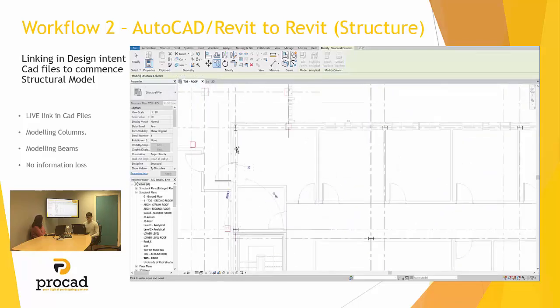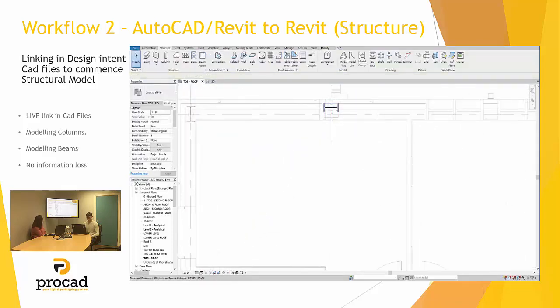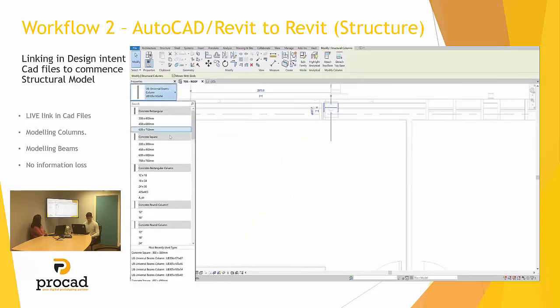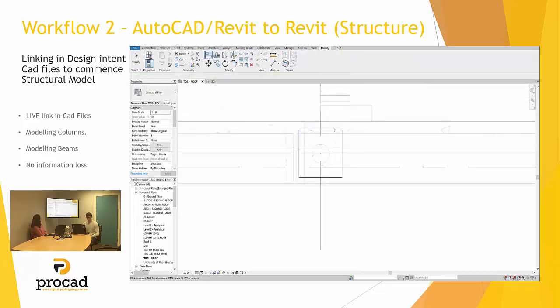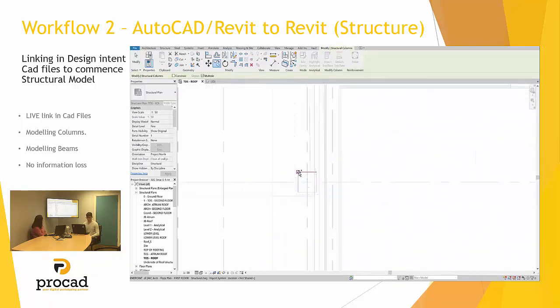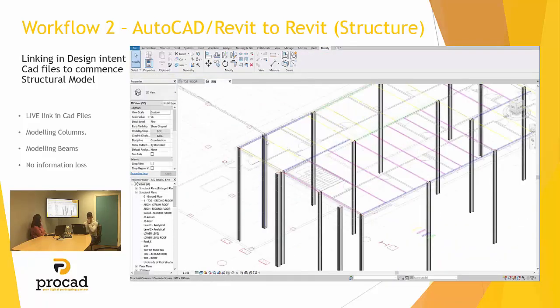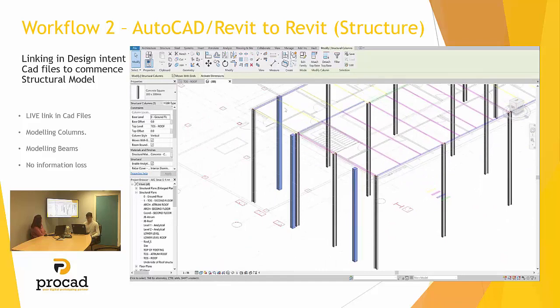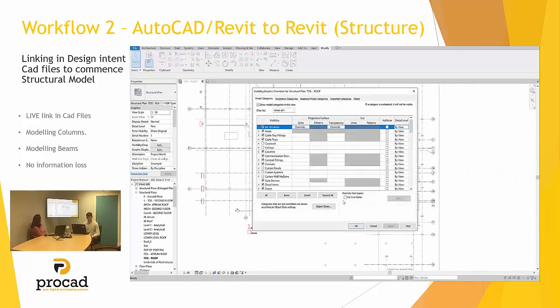Again, if you place a wrong column, in this case I'm going to put in a column where it needs to be a concrete column, just going up to your properties palette and selecting the correct one and then aligning to the correct position. Using the multiple option makes it a lot quicker. You can copy multiple columns at the same time. If you place them at the wrong level, you can easily go in, selecting them, going back into the properties palette and selecting the correct level that they should be at.